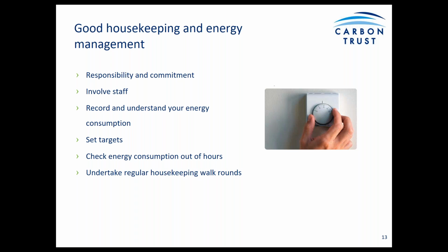Check energy consumption out of hours. So if a building is empty overnight, then it's quite often worth finding out just how much energy is actually being consumed when no one is in the building. A simple way to do this would just be to take meter readings at the end of one day and the beginning of the next. And then just have a look at the difference between the two readings, and this will show you how much energy is being consumed overnight. And quite often that is more than was expected. So it's, as I say, always worth a little bit of investigation on that point.